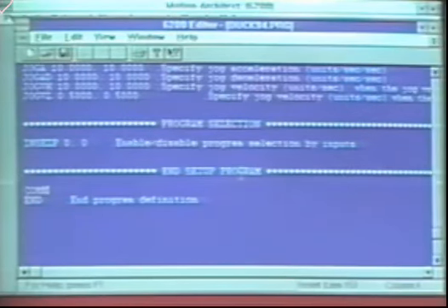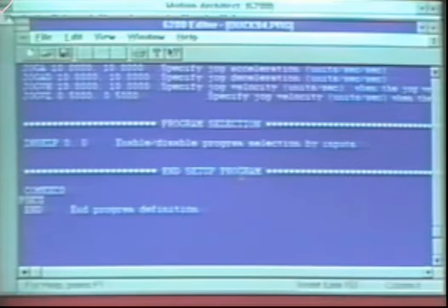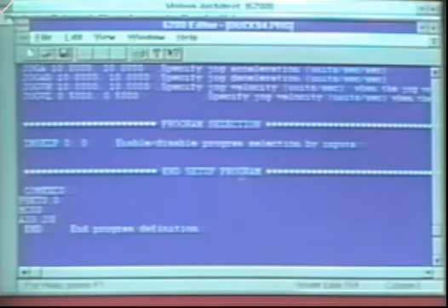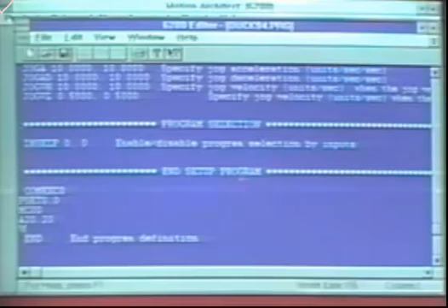This move will have a normal move and a continuous move. We will also be using the inputs and outputs we just configured. Remember that we defined output 3 as a programmable output. So we will have this turn on and off in between the defined move and the continuous move.